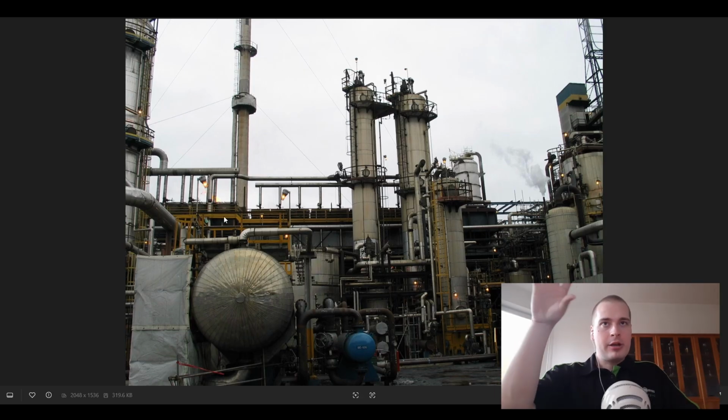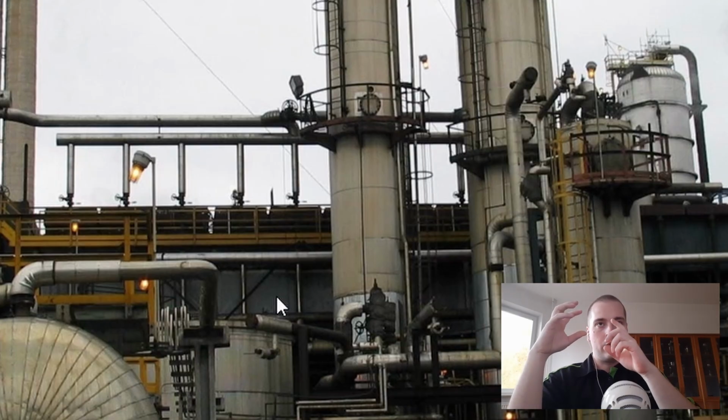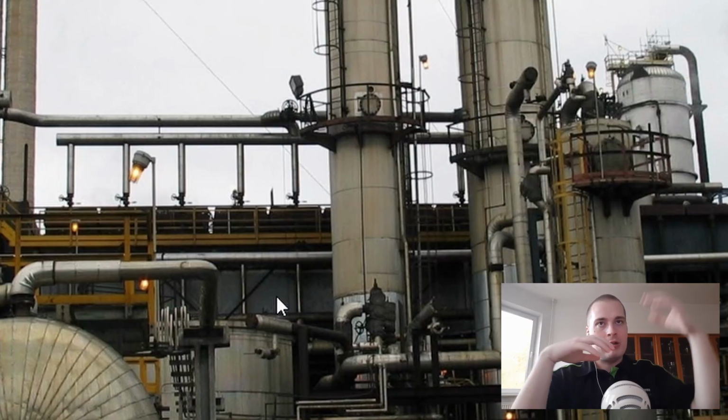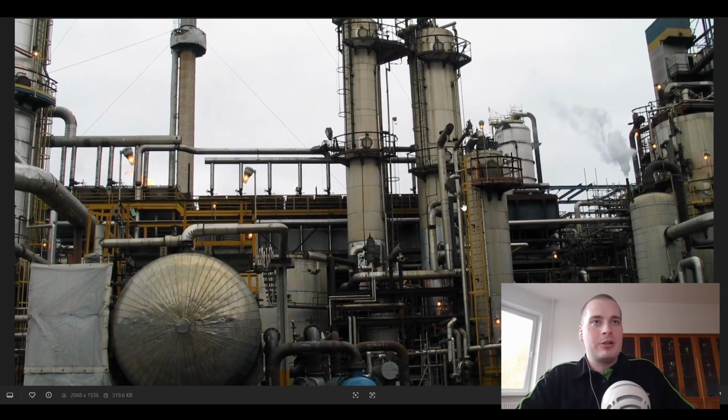And at the back there, on top of the piping rack, we actually have our coolers, which I was talking about earlier, the ones that have a lot of tubing in there, the fan at the bottom that spins and rolls the air, and then we have louvers at the top to control the amount of air getting in.